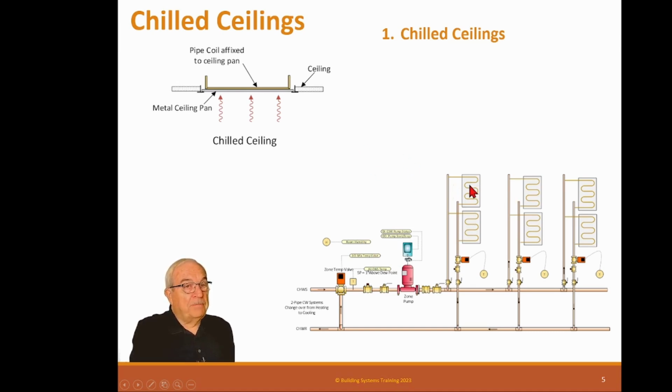Well, sometimes we didn't have enough ceiling space, you know what I mean, because there was too much junk in the ceiling. So we started trying to have people put the same things in the same tile. Like if you're going to have loudspeakers, put them in the same tile where you have a fire sprinkler head. We can't get it in anyway, so put other stuff there. If you need light sensors, try to put them all in the same tile so we can have more area. But even then, sometimes we didn't have enough area. So what we did is we upsized the ventilation system to be enough to take care of the excess sensible heat. A couple of times we've actually put these on the walls for that. It's a little harder to hide them on a wall, but you can do that.